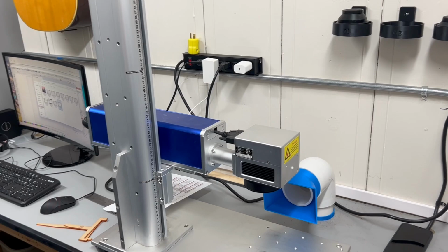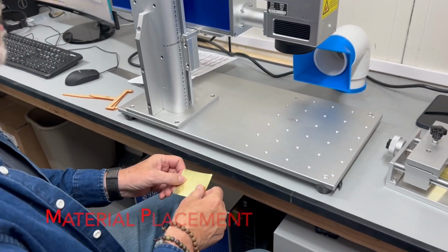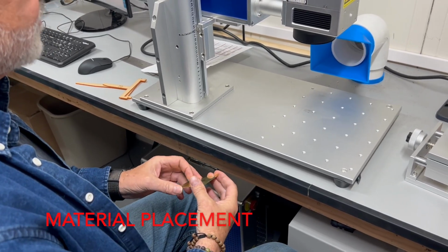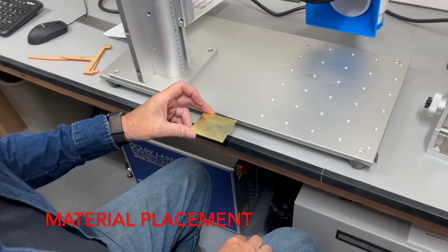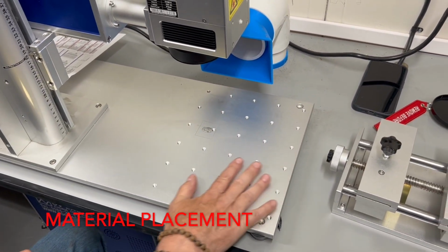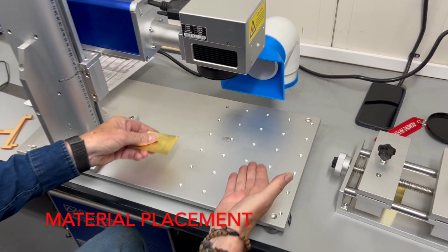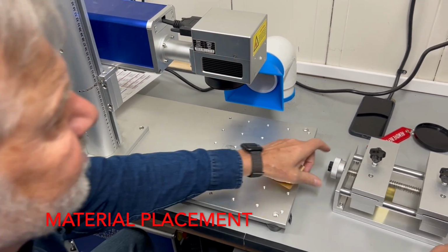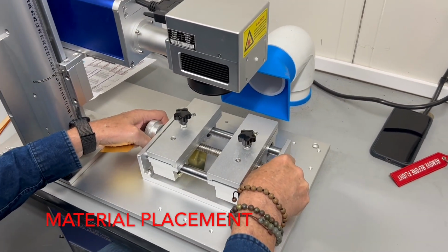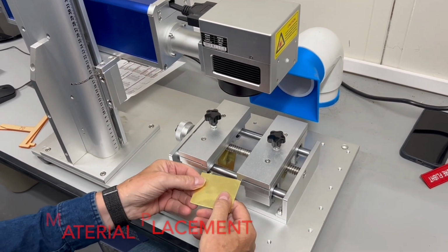All right, so now we're getting ready to cut. In this particular one, we are actually going to cut the brass. So like the CO2 laser, when you're cutting through a piece of material, you certainly don't want to be cutting into this bottom board here. So whenever you're going to cut through the material, make sure that you raise it up off the board. In this particular case, we have this little jig here, which allows us to take a piece of material and stick it in here.